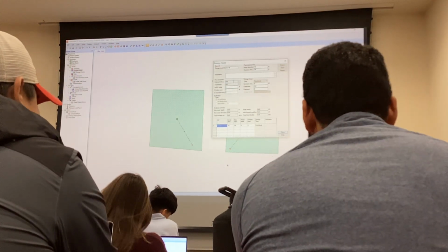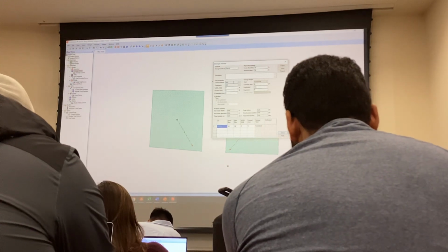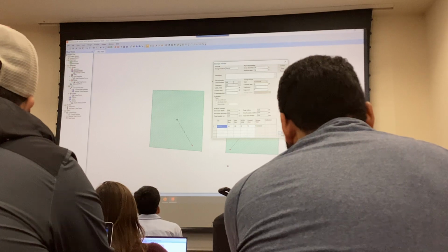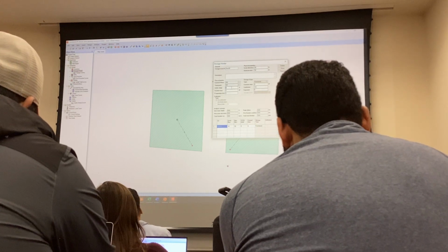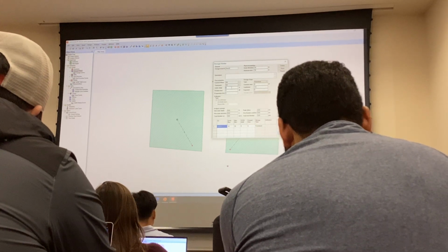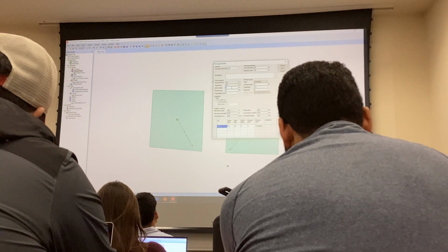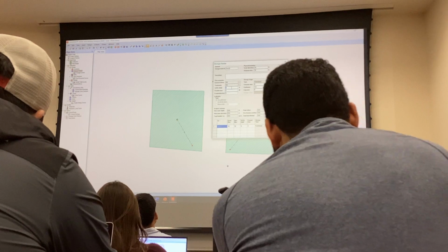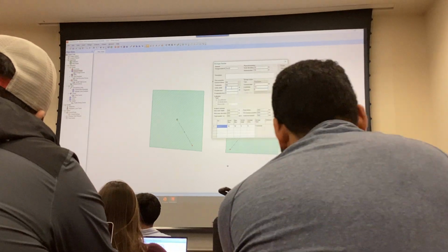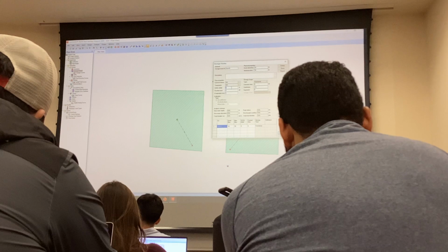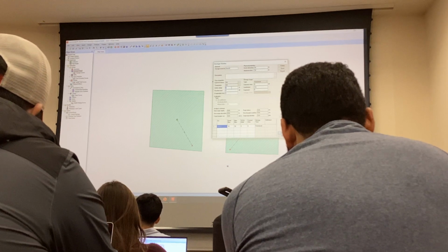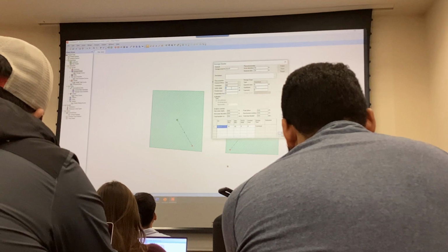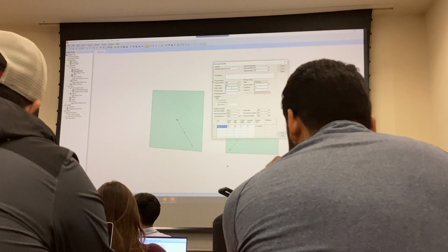So your detention basin can start by having an empty detention. So it's dry. If it's dry, then you specify the initial water surface elevation, not depth, elevation. You all know what the difference is, yeah? Water surface elevation means the elevation is referring to the mean sea level. It's not just any value.